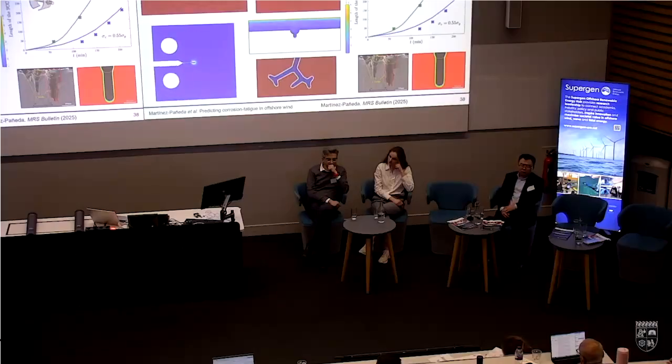And the Flexible FAN project gave me the opportunity to take this fundamental work and apply it to the specifics of offshore wind. And we did that through 3 sub-projects. The first one was aimed at understanding and quantifying the interplay between surface roughness and fatigue life. And this is very relevant for offshore wind because often we have a situation where we have our monopiles corroding, but then we protect them in a different region.